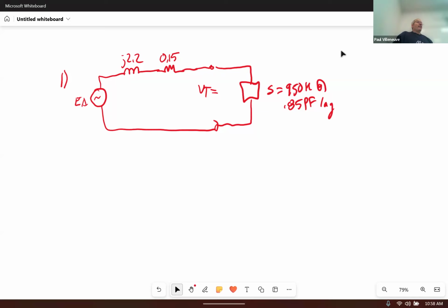Like almost any electrical system that you work on, it's usually really helpful to draw a schematic diagram, right? When we talked about synchronous machines, we said we need to develop an equivalent circuit of a synchronous machine. An equivalent circuit is something that is electrically equivalent. It's actually not the same, but it's going to give you the correct electrical results. So if you're going to use electric circuit theory, KVL, KCL, Ohm's law, to solve these problems, it's really helpful to draw a circuit schematic.